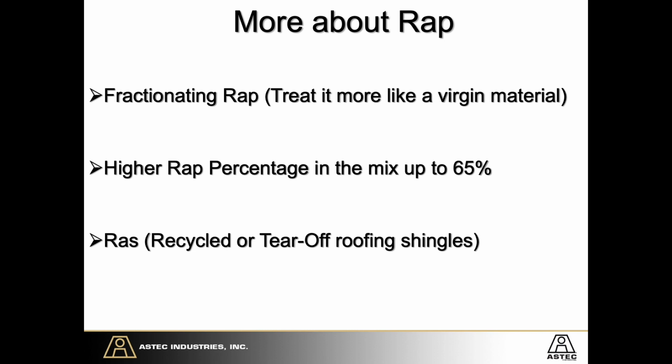Another thing we're seeing is higher RAP percentages, up to 65% RAP. Sometimes we even see a few people pushing it to 70 and 80. If you go over in Europe, you see a few 100% RAP plants. But most states now regulate somewhere between 15 and 30%, according to what state you're in. But on private jobs, it can go all the way up to as much as 65.